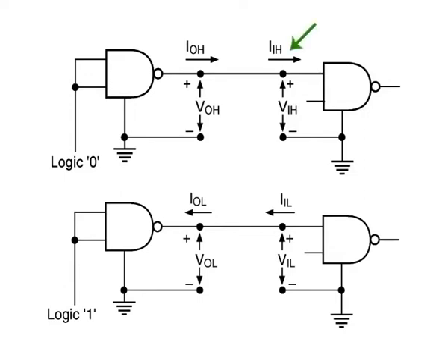High level input current. This is the current flowing into or out of an input when a high level input voltage equal to the minimum high level output voltage specified for the family is applied. In the case of bipolar logic families such as TTL, the circuit design is such that the current flows into the input pin and is therefore specified as positive. In the case of CMOS logic families, it could be either positive or negative, and only an absolute value is specified in this case.